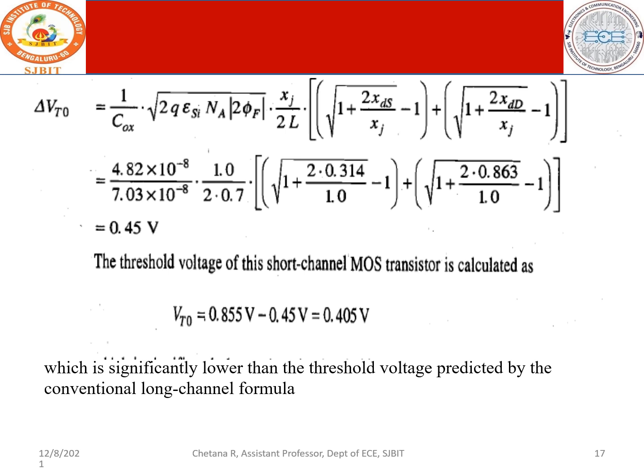So because of all these things, now we have concluded that the threshold voltage of an NMOS is given as 0.2 VDD, and for the PMOS it is given as minus 0.6 VDD. So of course we can take those parameters, but since we are learning about the threshold voltage, whatever the intricacies involved with the threshold voltage, right now when I simply said threshold voltage, it was clear. But right now we all have understood what are the different parameters which are involved in giving us the threshold voltage. It may be the work potential, bulk potential, charge, length, width, everything is involved in determining the threshold voltage.